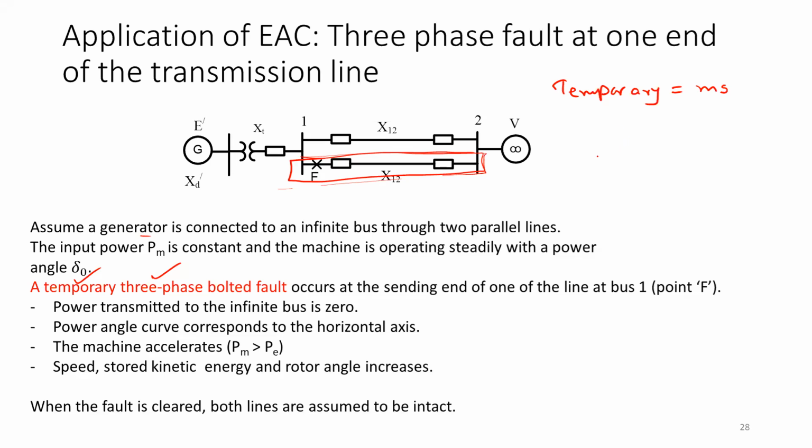So you see, when you have three wires carrying current, these are, say, three phases which are carrying the current. If you have a single-phase fault, that means one of the phases is suddenly grounded. The other two phases remain intact, so whatever current was going through them will remain as it is.